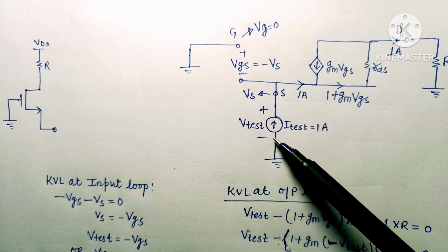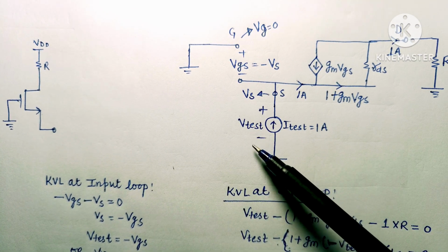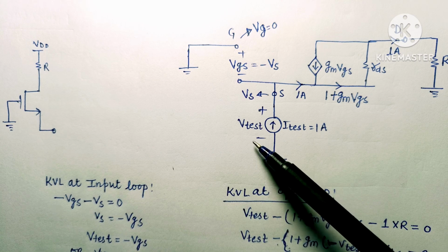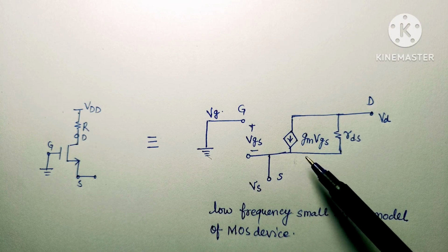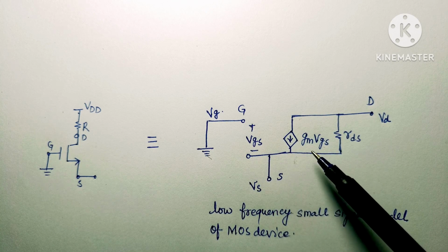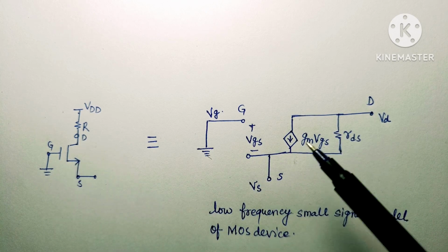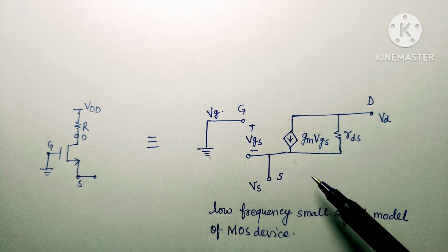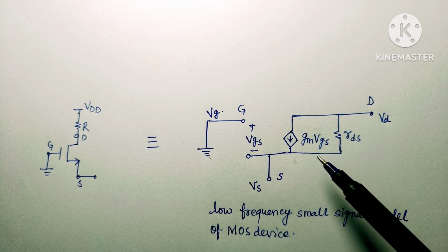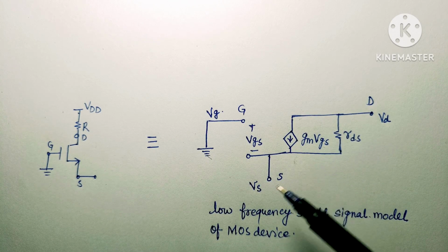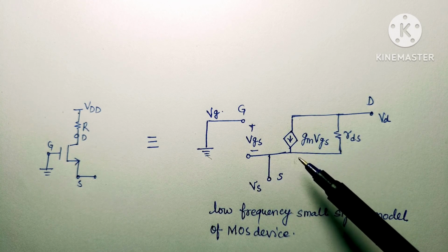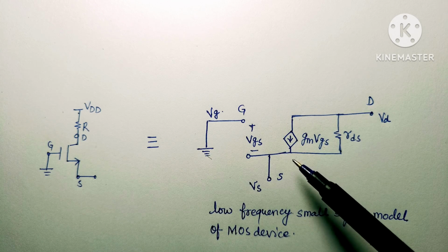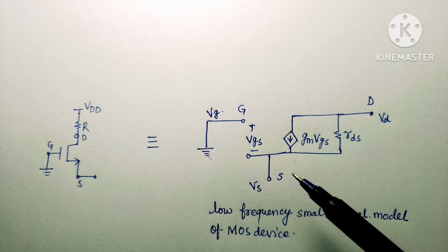So in this question, as we can see in the equivalent model of the circuit, there is no independent voltage source applied in this circuit, so we will find out this Thevenin's resistance of the circuit by using the second method, where only dependent source is connected to the circuit. So for this sake we will apply a test source and find out the Thevenin's resistance.